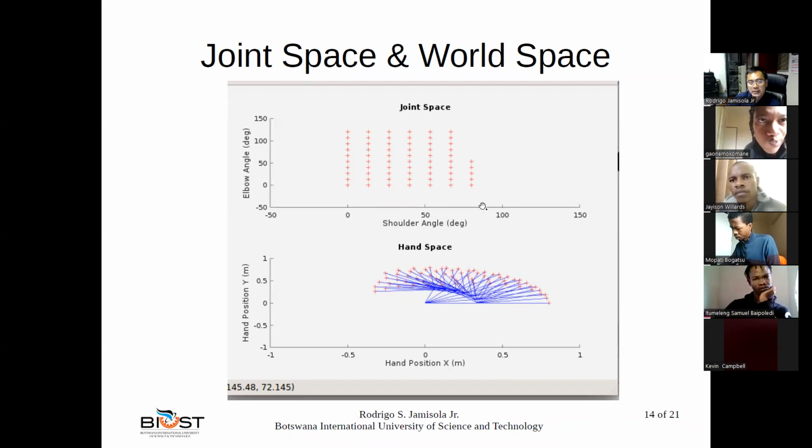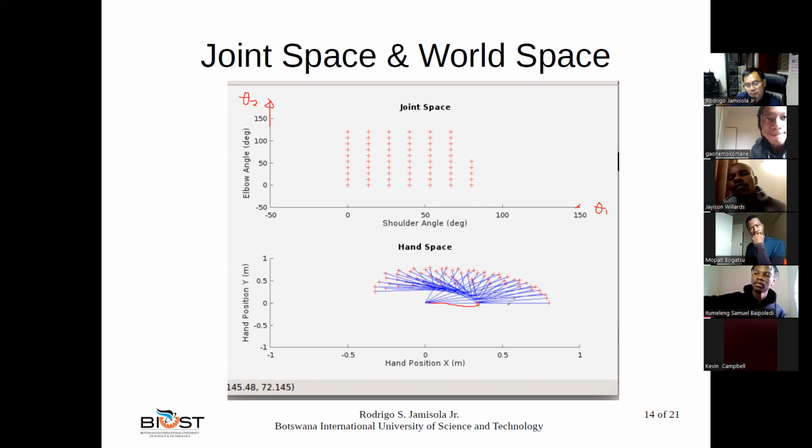So joint 1, in this case, we now change the coordinate of the axis. Last time we had a time element, now we change it. So this is the theta 1 axis, and the other one is the theta 2 axis. Okay, so we just plot them. We make theta 1 zero, that means this was flat, and then we sweep theta 2. Theta 2 goes up like that. So theta 1 is zero, theta 2 will go up, the same thing as the single degree of freedom joint.